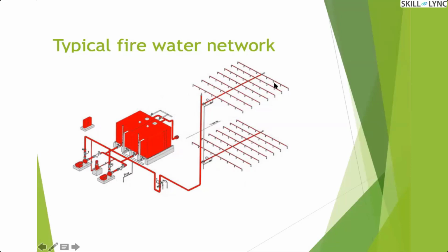So based on that pressure, you can also calculate the flow rate at each nozzle. What generally happens is these nozzles will have higher flow rates, but these nozzles will have lower flow rates because they have suffered the longest hydraulic path. So this will have the lower inlet pressure, and so this will have the lower flow rate. Based on your required flow rates, you should be able to meet the required flow rate even at this location. So accordingly, you should develop the pressure from the pump, and accordingly, you should also meet the flow rate.